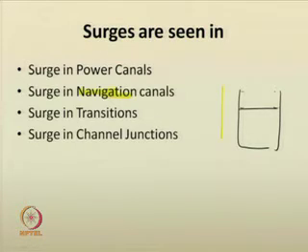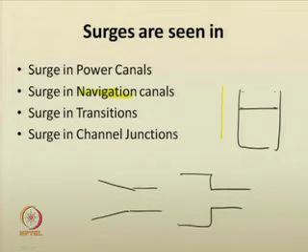Surges in transitions are also there. Say if there is a change in the width of the channel all of a sudden, you use the continuity equation there to analyze those things. Using continuity and momentum equations, how surges are formed at channel junctions is also analyzed.